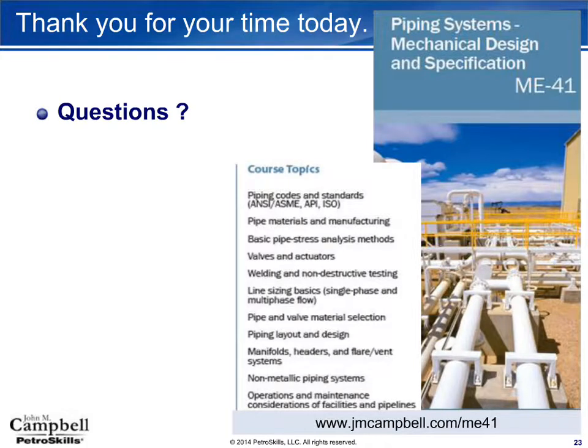As an application example, the Alaska pipeline had massive resonance issues that they had to address, that pipeline being above grade, with wind and essentially a vibration issue. We see similar things when we have spanning in subsea pipelines. In an onshore situation, we get resonance inside piping systems, especially around compressors. And usually we will do third-party analyses to make sure that the excitation frequency of the compressor is not driving the natural frequency of the piping.